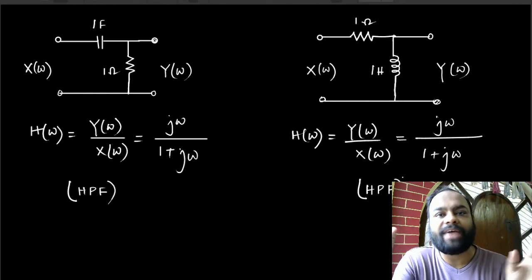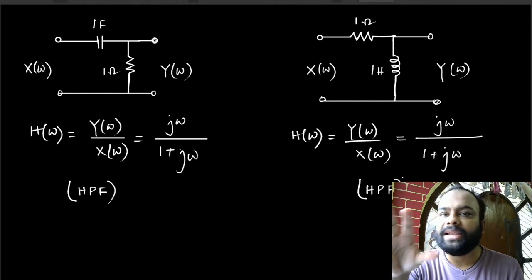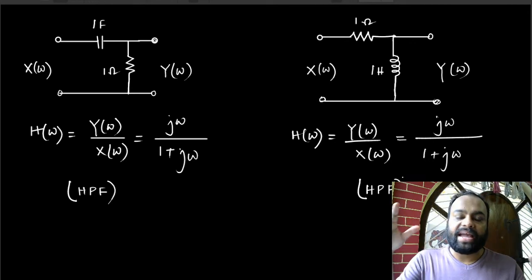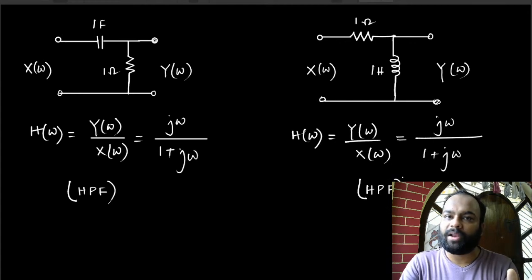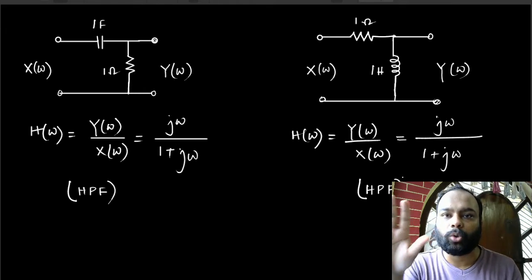These circuits would behave identically from the perspective of the input signal and the output signal, because they have the same impulse response. And I said, if I am dealing with a linear time invariant system, the impulse response is entirely responsible for the behavior of the system. We can figure out everything about the system by just looking at its impulse response.